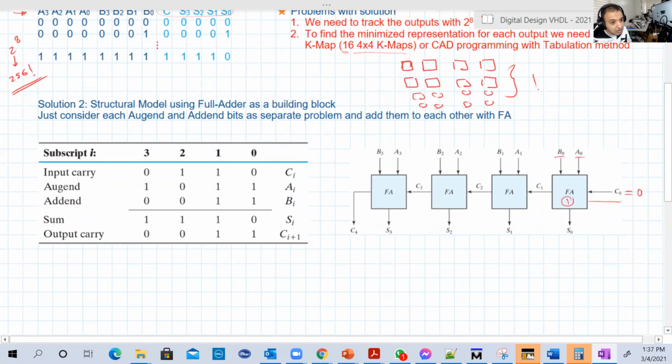And you must not leave it floating. You must connect it to something. Any input left floating in the circuit might pick up unpredictable noise that may cause it to read as a logic 1 or logic 0. So you must connect it to 0, to the ground of the circuit. Basically, this is a circuit: 1 is just the VCC of the circuit, the high voltage, and 0 is just the ground.